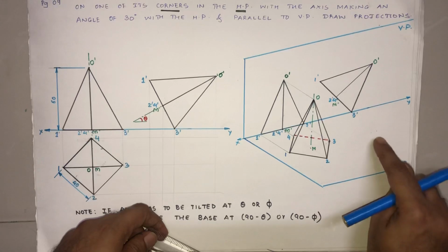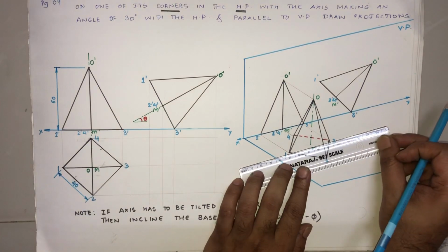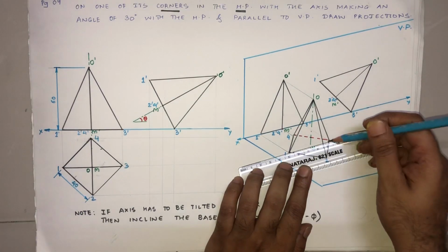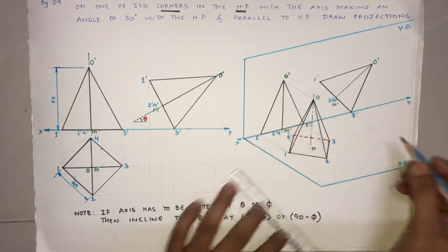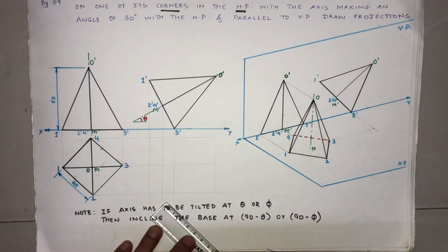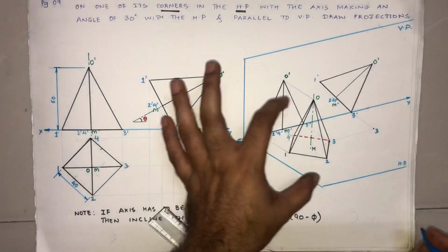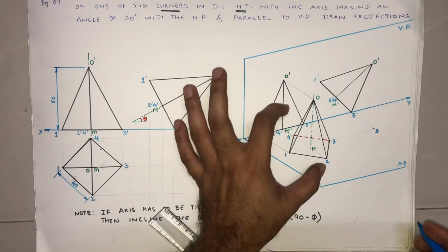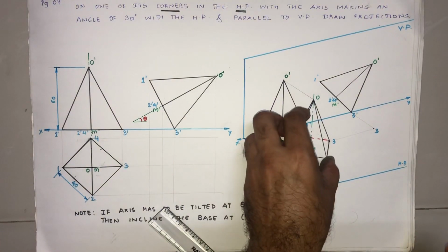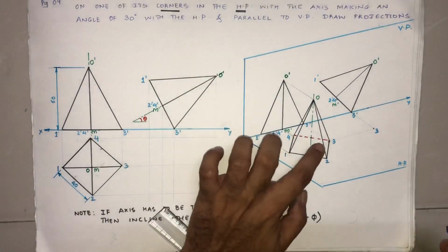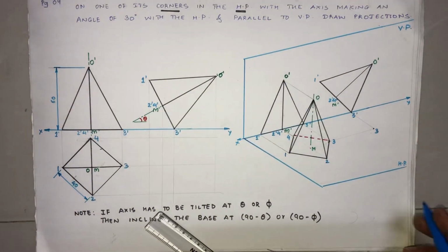Now, if I would want to get this point, this is what I have been doing. I have projected this here, projected this point number 3 here, and I'm going to project this point here. The intersection of this is going to give me the actual point number 3. Basically, remember, this was our first step. It is not that we have lifted the solid and kept it here. We are tilting the solid right here in this place only. So instead of showing it in the same alignment, I'm just showing the same thing here.